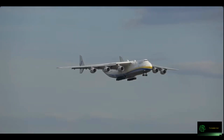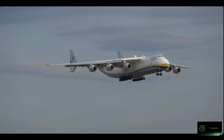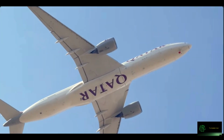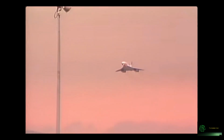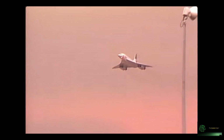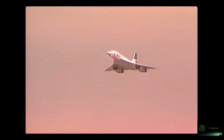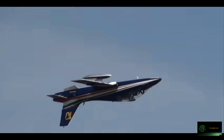VD or design diving speed is the maximum speed considered during the aircraft's structural design and testing. It represents the highest speed the aircraft is built to withstand during certification flight testing, typically in a controlled dive. VD provides a safety margin above the maximum operating limit speed.